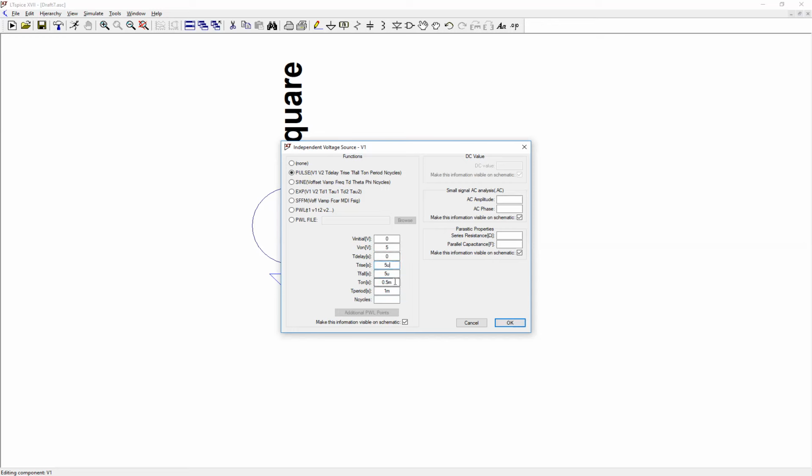And again, the rise time and fall time may also be smaller, or larger. I use 100 because again, I want it to be negligible with respect to T on, okay? This is my personal rule, but you can use your own rule. The important thing is that it looks like a square wave in the end.